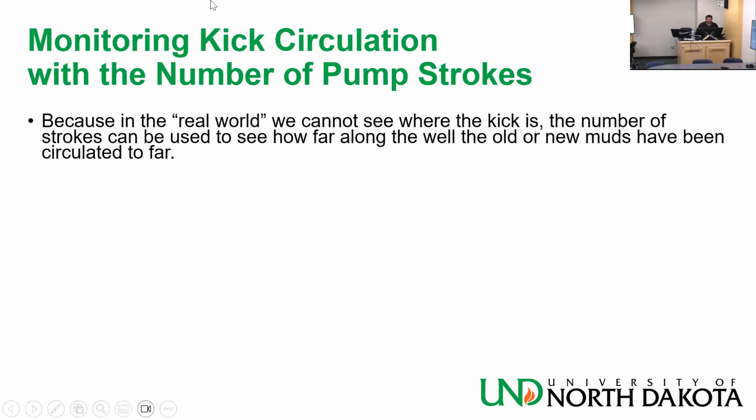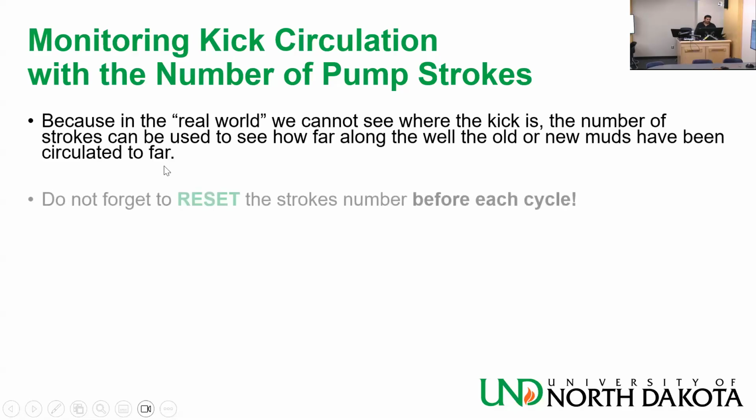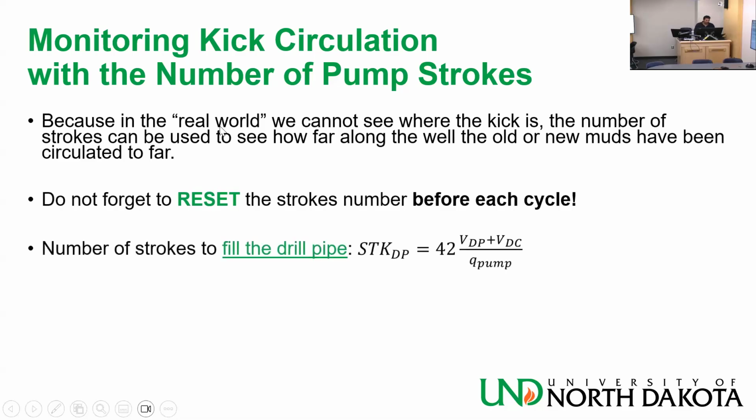Because in the real world we cannot see where the kick is, the number of strokes can be used to see how far along the well all the new mud has been circulated so far. Do not forget to reset the strokes number before each cycle when you do your simulation.